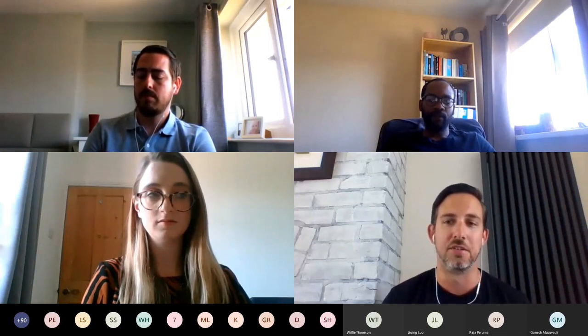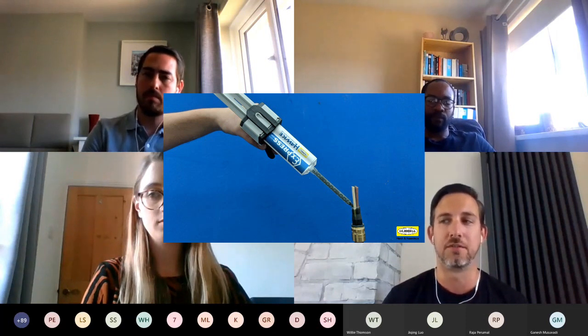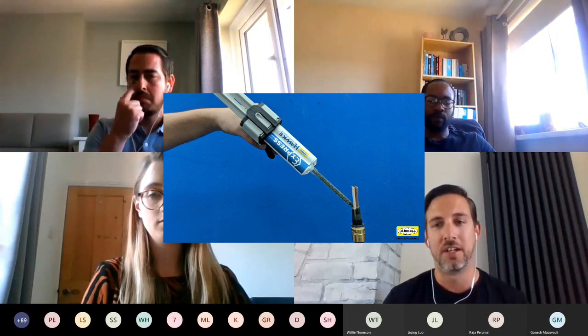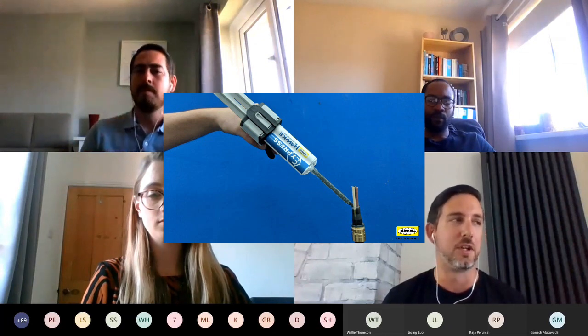We've also got our new liquid express resin. This starts life as a 2-part liquid in a cartridge, and you dispense it by hand. The cartridge mixes the material as it comes out, and you pour it into the gland itself, and it will flow around the cores. It's a nice dark colour with a high contrast, so you can actually see it flowing. You can understand how much material you've got in the compound pot, etc.